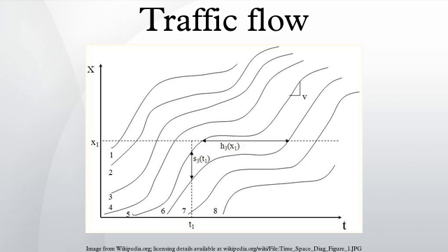However, downstream of X0, the roadway narrows, reducing the capacity by half, to below that of state B. Due to this, vehicles will begin queuing upstream of X0. This is represented by high-density state D. The vehicle speed in this state is the slower Vd, as taken from the fundamental diagram. Downstream of the bottleneck, vehicles transition to state D, where they again travel at free flow speed Vf.